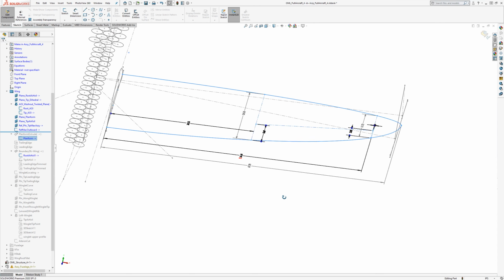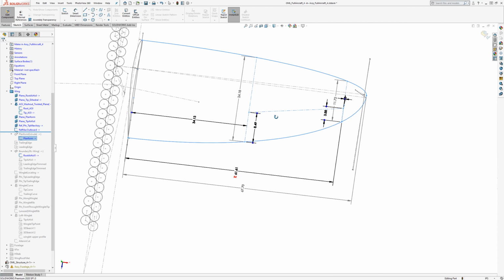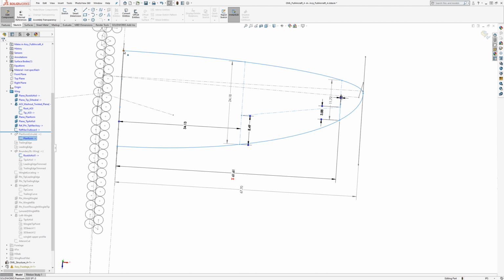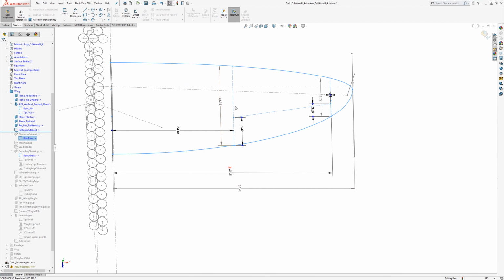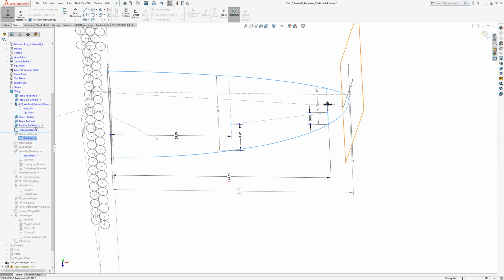And the planform itself is two partial ellipses: the leading edge portion, which I think is a 30% chord ahead of this point, and then the trailing edge portion, and some markup geometry for where, for instance, the ailerons will be and things like that.